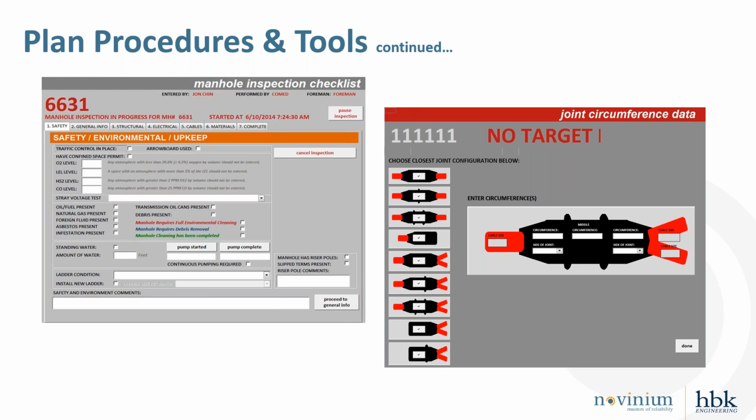In the ComEd program, we designed the capture tool to guide our crews from the initial steps that could be the safety setup for the manhole, in other words, checking the atmosphere within the manhole, but also then drill into something as specific as checking lead joint diameters to detect potential collapse or expansion of the joint components, which you can see on the right side of the screen.